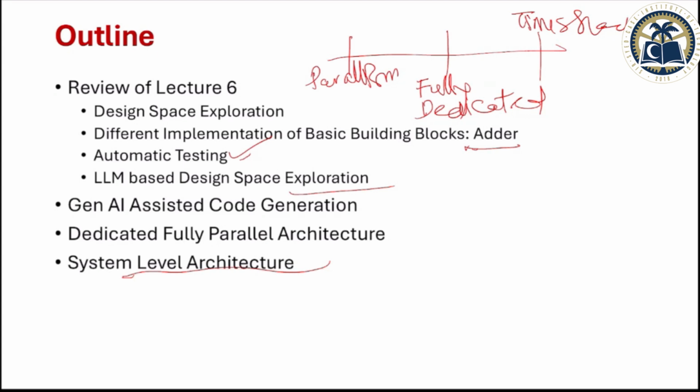The third, which is very interesting, is where you need to do a lot more than what is there in the algorithm, okay? So this is where you have to exploit parallelism. You want to run your hardware 10 times faster than the clock rate, for example. Let's say you have a clock rate of 100 megahertz and you want to run an architecture processing 400 mega samples per second, which is 4 times higher than your clock rate.